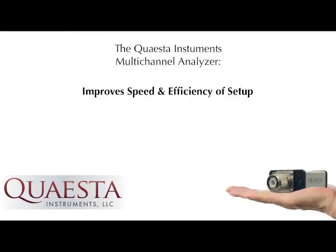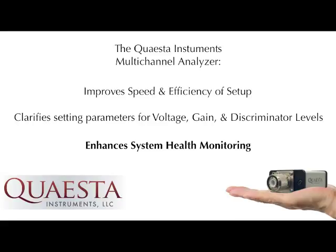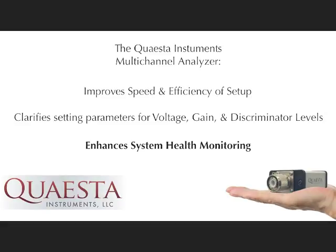In summary, the benefits of using a multi-channel analyzer with your neutron detector include ease of setup, clarity in setting detector parameters including voltage, gain, and discriminator levels, and the pulse height spectrum provides useful information for long-term health monitoring of your neutron detector. Changes in the shape or location of the pulse height spectrum can be indicative of problems with the system.